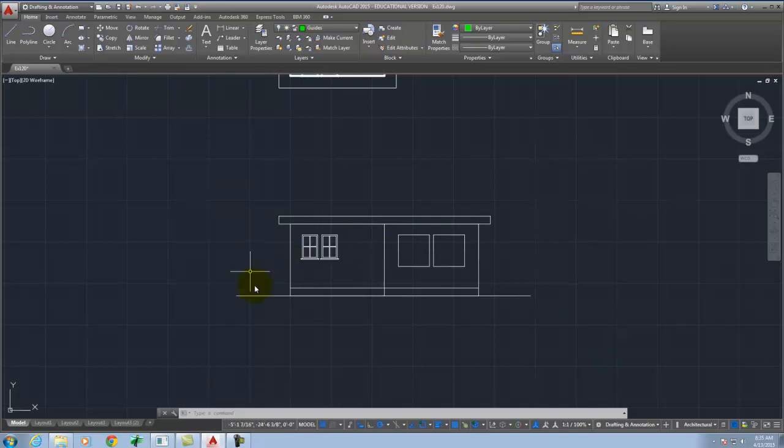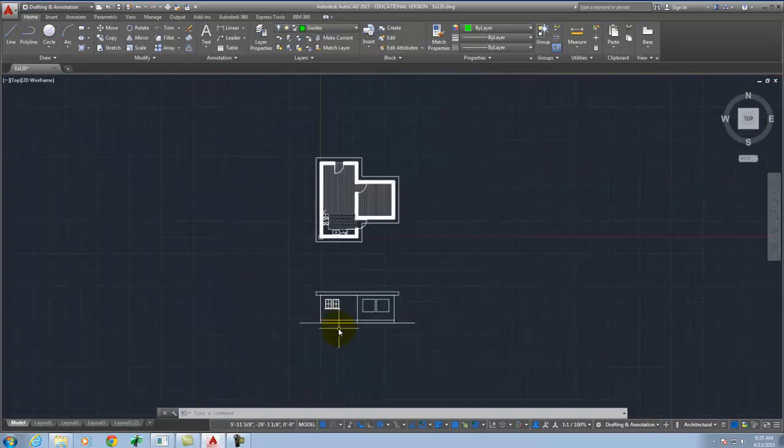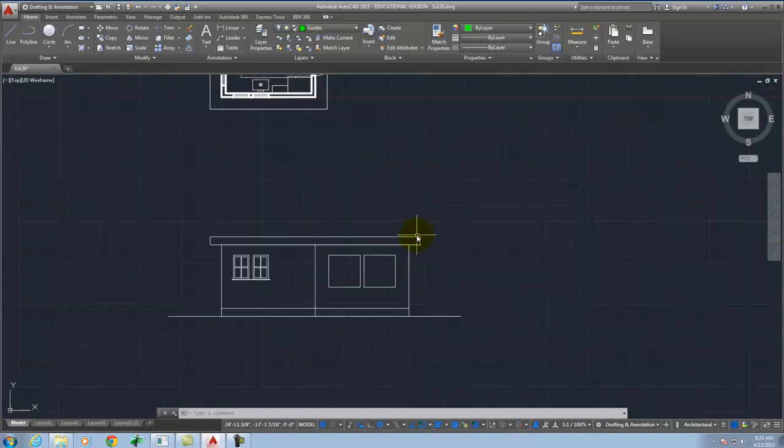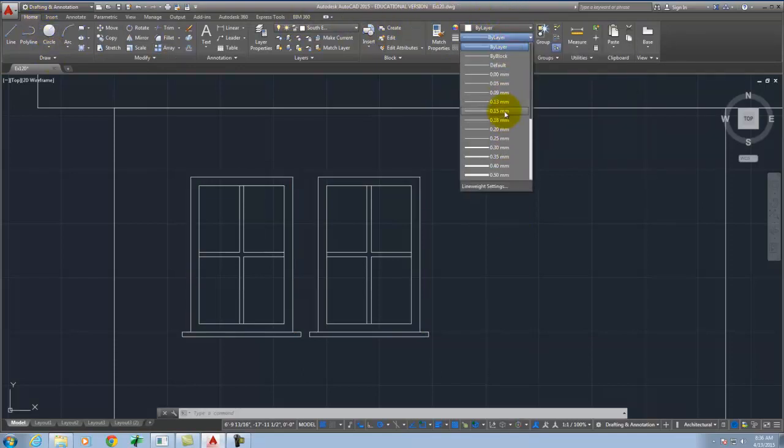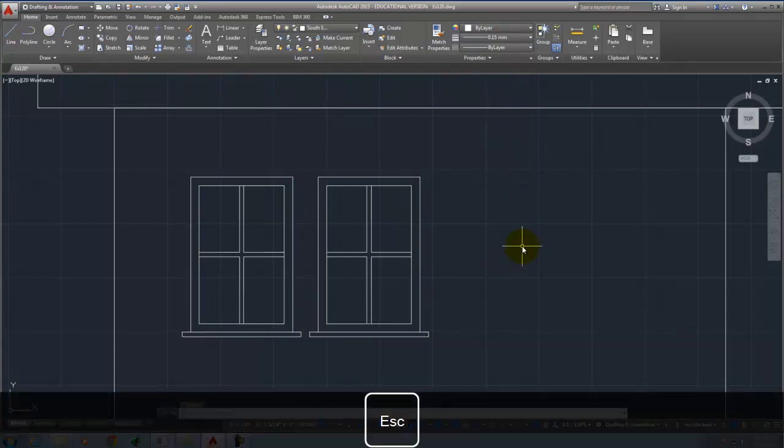And so you're going to be working through that, adding more and more detail, just like you're adding more and more detail here. Now, once we get to this piece, we're going to think through the line weights a little bit. I only gave you a plan of what line weights should look like, but you can do the same thing. So we could make, say, the window frame here and the window frame here a little bit thicker, maybe 0.9, right? And to do that, I'm going to come up to the properties. I've selected the objects there, and I'm coming up to the properties here, which is in the home ribbon, and I'm just going to change the line weight to be a different line weight. So we could say we want it to be a little bit thicker, right?